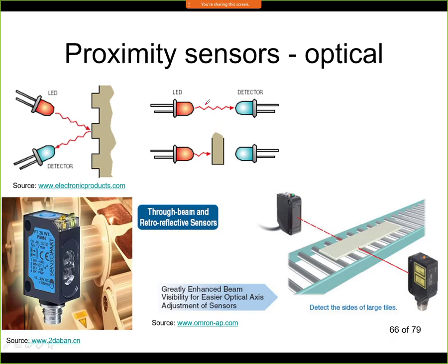We have a second option, and here we see that we have an LED. This produces a beam of light, and this is my detector. The optical system is not shown, but you need it anyway, because if you do it just like this, then the angle where this radiates will be very large. It could be something like 90 degrees, so you would have some radiation field like this, and it's not a beam like that. So in order to have a beam like this, you would need a laser diode.